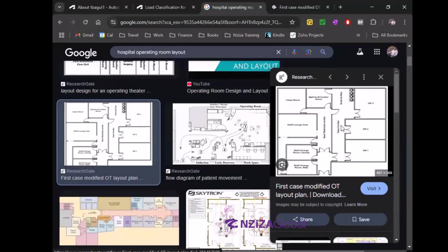Then there is a corridor for those operating rooms. This corridor is not accessible to any of the guests or visitors. Only the doctors who are going to operate, the nurses who are going to assist, and the patient who is going to be operated can access it through this door. So this area will always have low CFM supply, even at the highest possible heat load, as compared to any of these three operating rooms. There you go. Clean corridor.